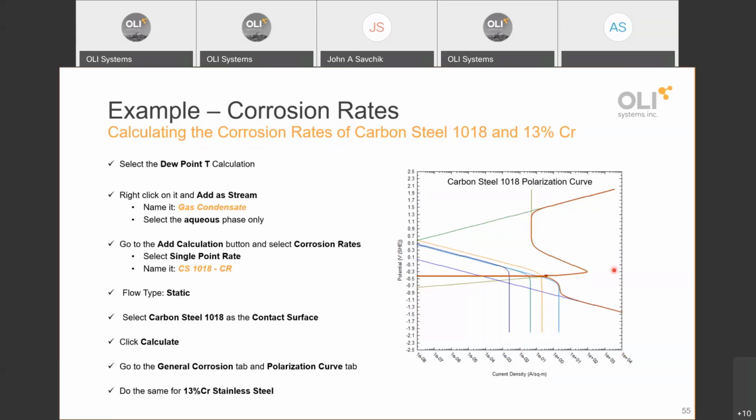The peak current density is calculated with another equation that we have in the software specifically for peak current densities, and it can vary depending upon composition, let's say chloride concentration, etc. So sometimes they match and sometimes they don't. They will match when we're calculating that peak current density under the same conditions.